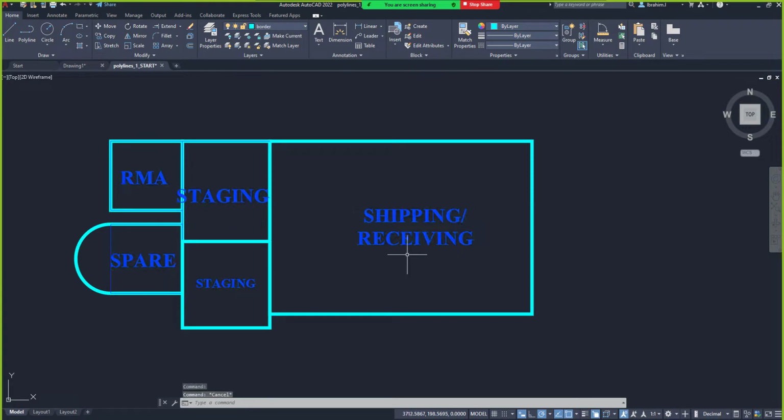How do you know? Escape. My crosshair is currently not active, right? I select the first one on the list. Immediately it is selected, I just move my mouse to the next one. You can see it's showing plus. That means AutoCAD is asking, should I add this to it? Then I click on yes. Add it to it. When I move it to this next one again, can you see it's asking me plus? Add this to it again, add this part to it again. Now all these texts are selected.